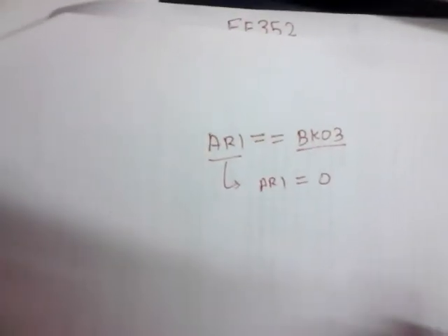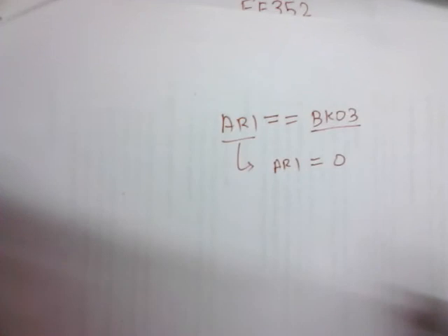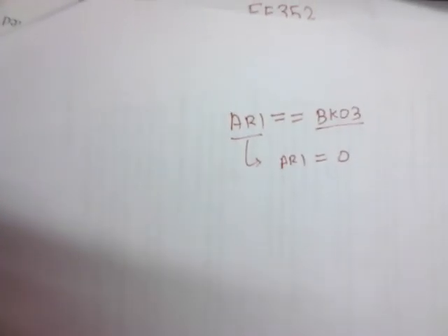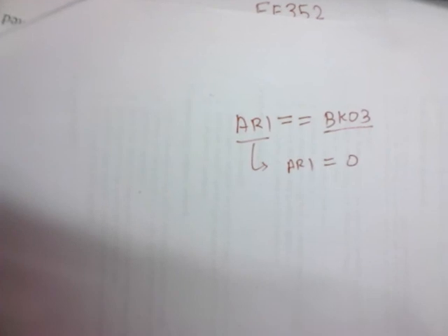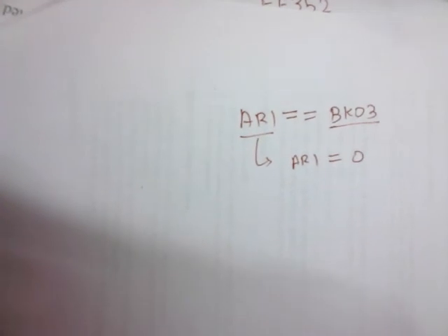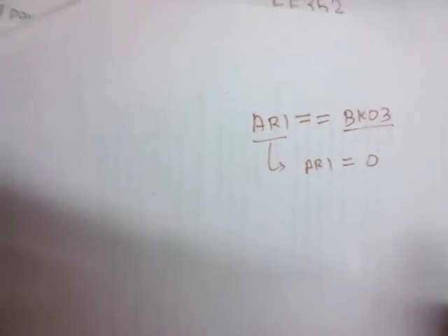So don't worry about boundary conditions. We don't need to check whether our old index value has reached a boundary or not. It will automatically be implemented in circular fashion by hardware.